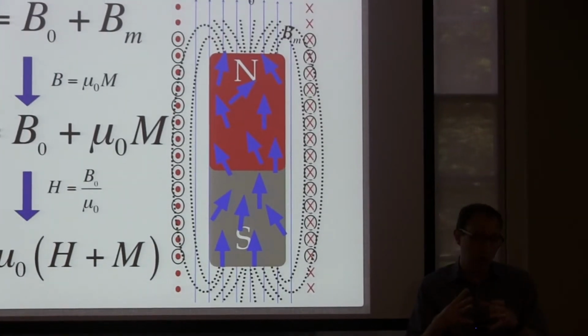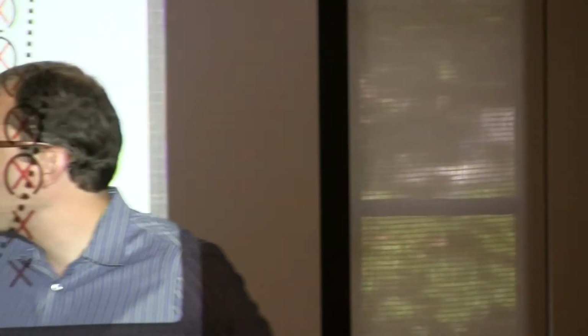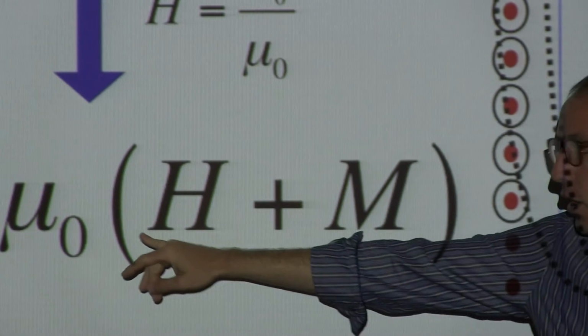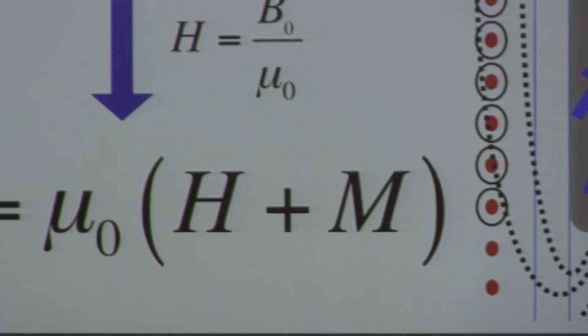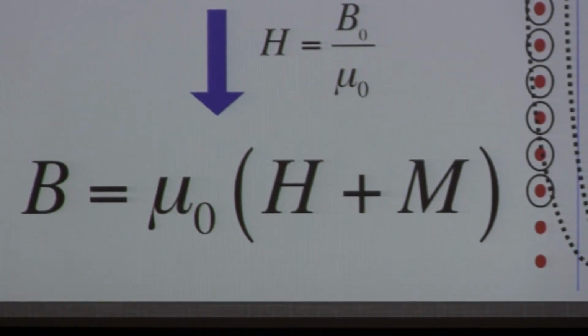So even if we've got a solenoid full of air, we have to actually account for the magnetization of the air molecules in there. So how magnetic is air? Not very. Now, absolute vacuum would be a lot better, but we do need to account for that a little bit. So that's where this B field and H field come in. If you have something that has a very low magnetization, you can actually reduce this term, and so now B becomes equivalent to the permeability of free space times that H field. And so that's how understanding the magnetization of the material plays into that.